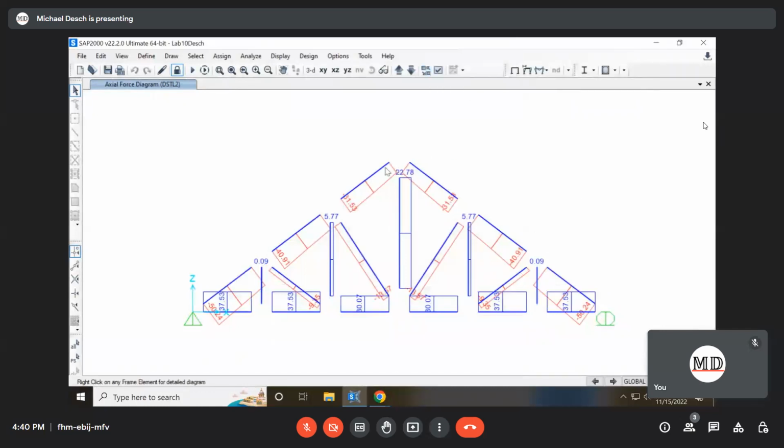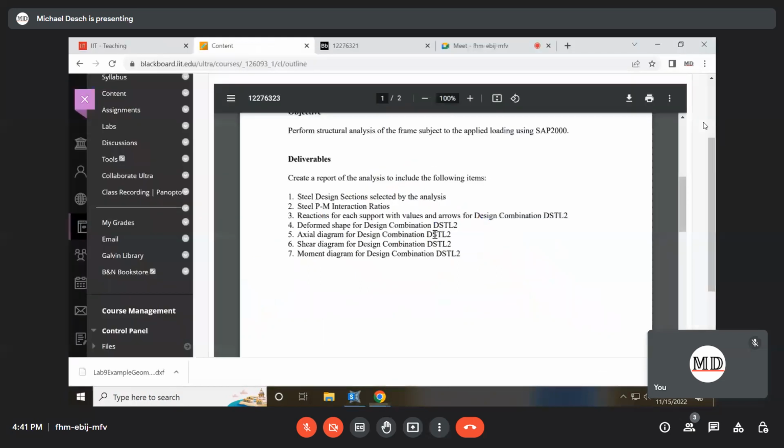And as you can tell here, because we have distributed loads on these top trusses, we have a non-uniform axial load here. So the further down we get on our truss, the bigger the axial load gets because we have more and more distributed load feeding towards it. And in each of our web members here, those should be pretty uniform. They'll be slightly non-uniform due to self-weight, but pretty uniform mostly. So they all should be trapezoidal.